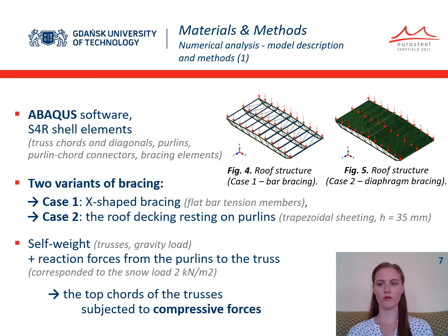The load, corresponding to self-weight of the trusses, was applied to all truss members. The snow load was taken into account as the reaction forces from the purlins to the trusses.